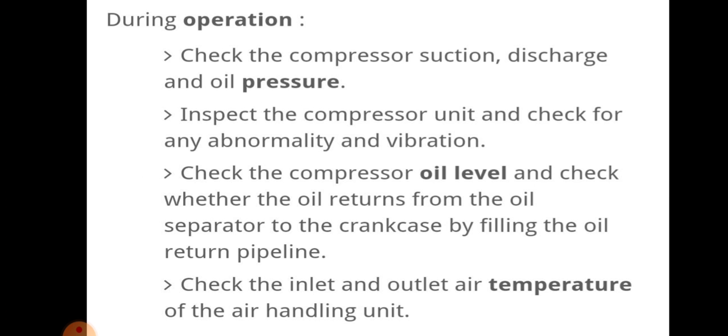During operation, we need to check the compressor suction, discharge and oil pressure. Inspect the compressor unit and check for any abnormality in vibration. Check the compressor oil level and check whether oil returns from the oil separator to the crankcase through the oil return pipeline. Check inlet and outlet air temperature of the air handling unit.